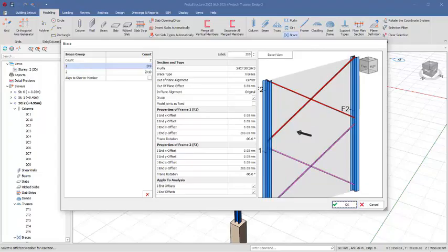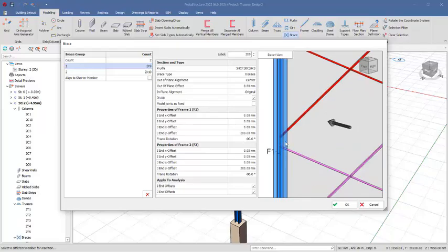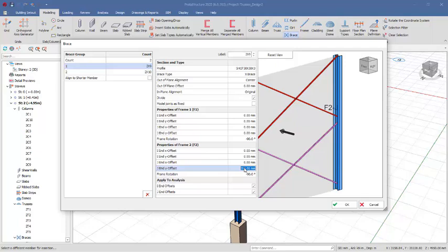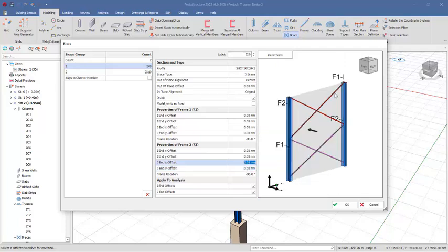So in this dialog, for the count 1 right there, get it selected. We really don't want to have this space here because of connections. We want this to be close, so that is why in the J and Y offset you have to change that to 0 and click outside to bring this close to this member. The same thing is applicable here. Come over to this provision, change it to 0, just as I explained earlier.